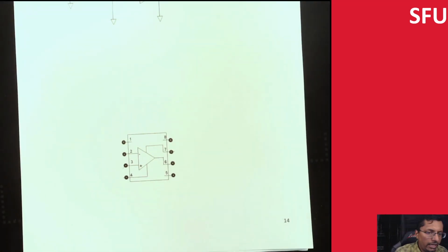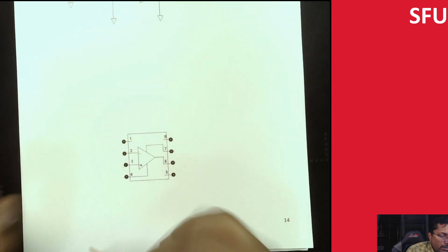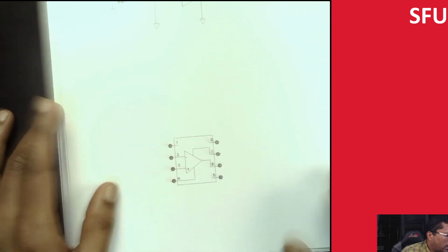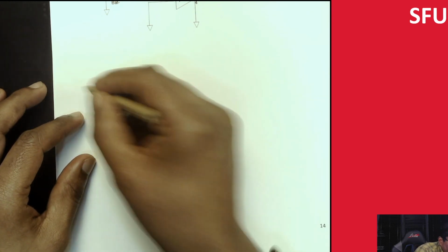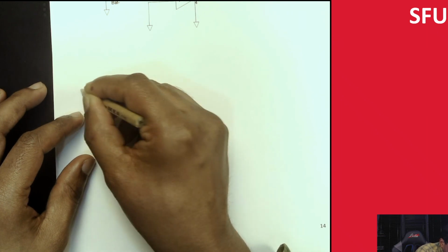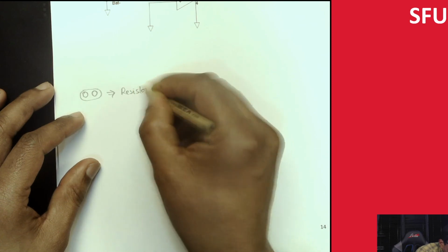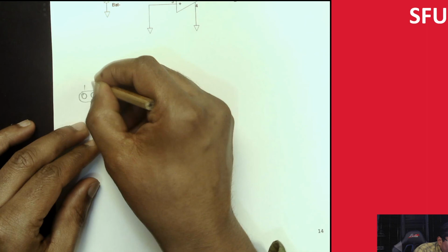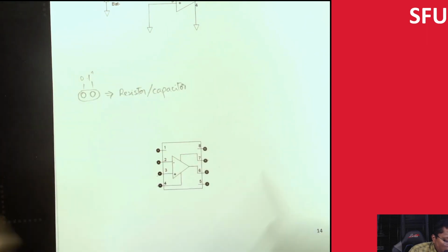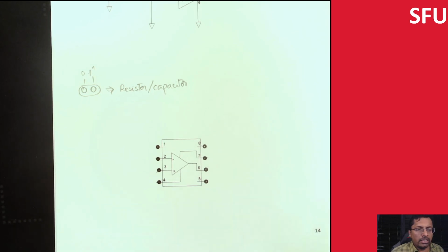So let's switch here to the document screen and do a manual circuit board. A quick note: we wouldn't need too much space, so you could have written stuff here and had some notes regarding the size. The other important thing to note is we want to make sure that the wires don't cross. So we draw this for the resistance. It basically denotes a resistor or capacitor, whatever component you would need. This is assumed to be say 0.1 inch, about the same distance between pins, and this is spaced about 0.4 inch. I've scaled this up several times so that you can actually create the drawing, but you're going to assume that when you create it, it's about the same distance over here.